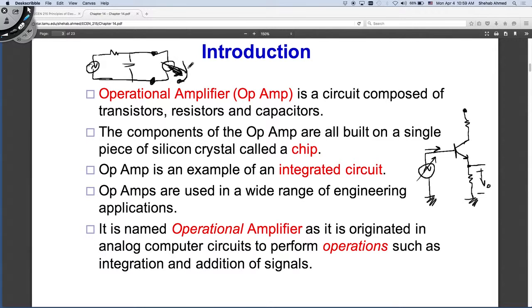For example, let's say this is a motor. This case is not practical, because here I have a sensor. I do not have a generator really. I have a sensor that provides some signal in a certain frequency range of interest. When it's low frequency, this circuit, my low-pass filter that we studied in the previous section, allows the signal to pass through as it is.